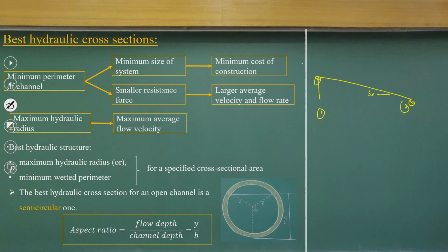Okay. So, a Q amount of discharge has to go through it. Okay. So, this Q is a design parameter, what are we looking at? Design parameter. First is shape, right, we can choose it. Okay. Slope is more or less fixed because the endpoints are fixed for us. So, one is shape: you can have rectangular, we have trapezoidal, you can have semicircles or circular pipes. So, the shapes can be different types, that is the option with us.